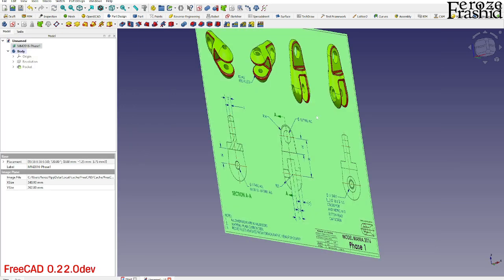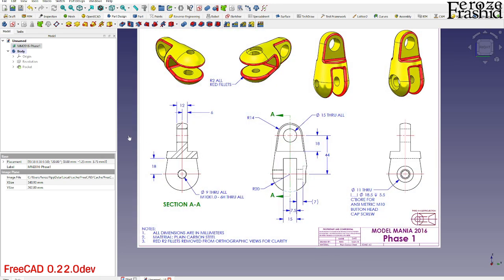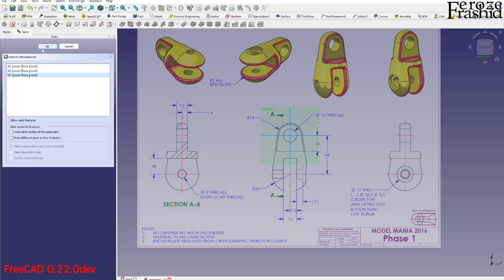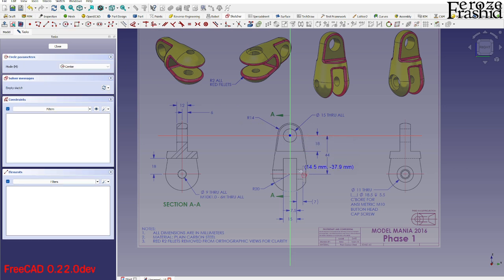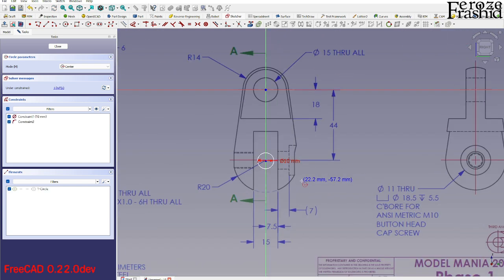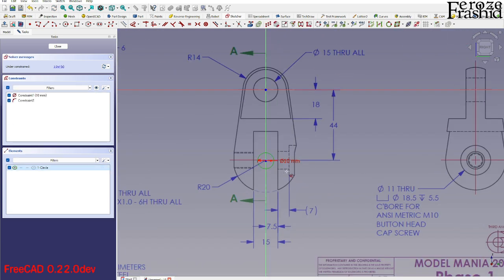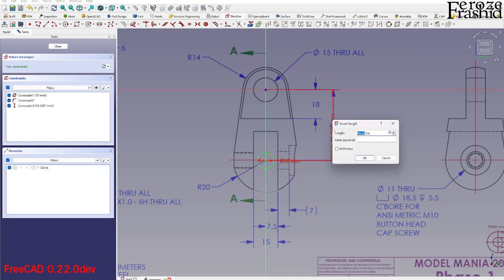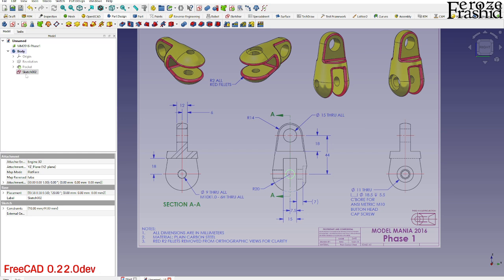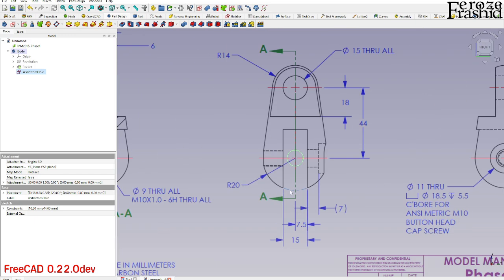And I will go ahead and change this image to the YZ direction, and then do a sketch on the YZ plane, just a circle right there. So it will be just a circle, say 10 millimeter diameter. Now diameter doesn't matter because we can address that later on. So it doesn't matter as long as it is at the right center, which is 44 millimeter down from the origin. And that one, I'm going to go ahead and say sketch bottom hole. So that hole is a technical term.